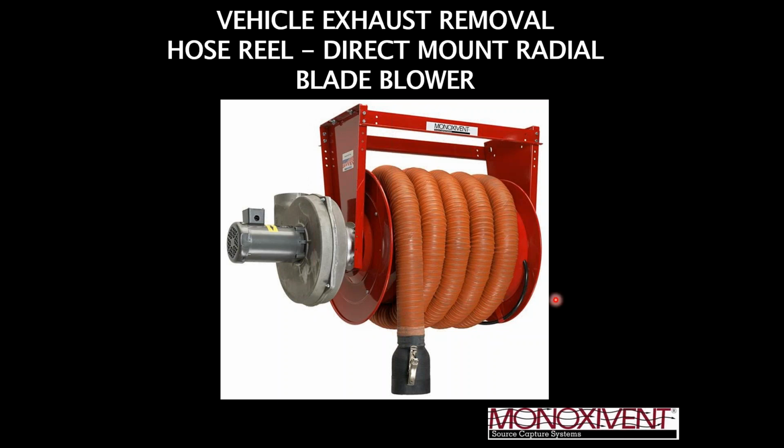Now, with all of that being said, I do not have to have a direct mount fan to utilize that type of a start system. So let's say I have 5 hose reels and 1 central fan. I would put the DMS HR switch on every hose reel, and the first hose reel that brings the hose down starts the fan, but the fan does not turn off until the last hose reel has had the hose retracted.